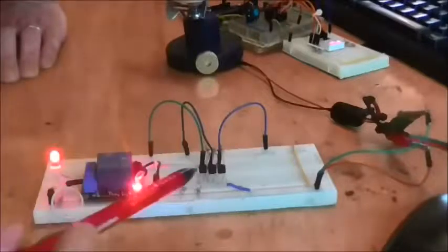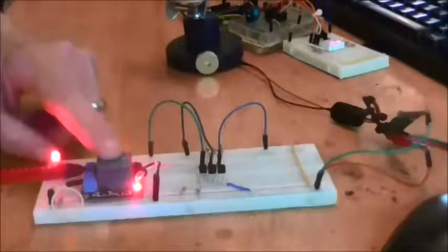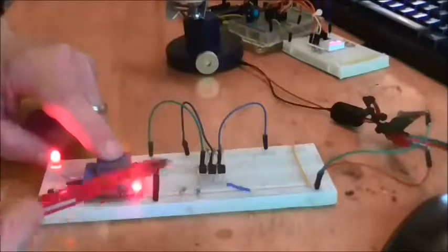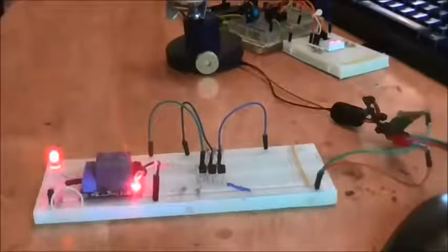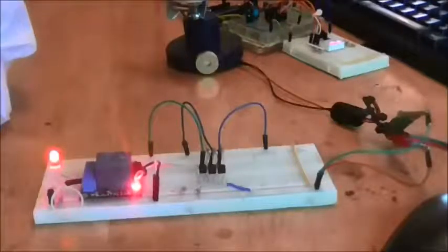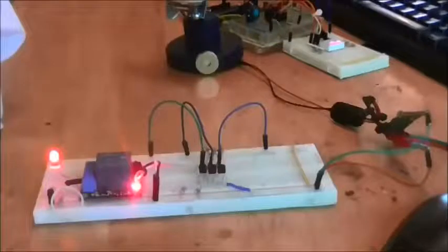With a relay, I can use the AND gate to work the relay and keep the output from the relay separate from the input to it. And this has another consequence. This means that I can actually use 9 volts. And I want to use 9 volts because I've got an eye on the market. So I can put a 9 volt siren in and make it a portable device as well as a static one, so it can work off batteries.